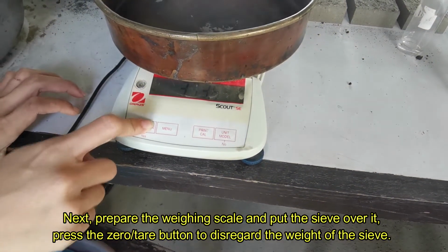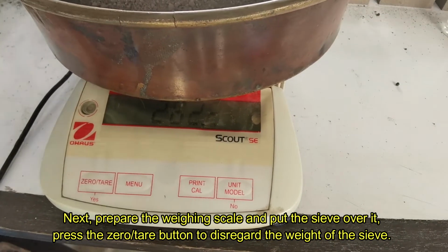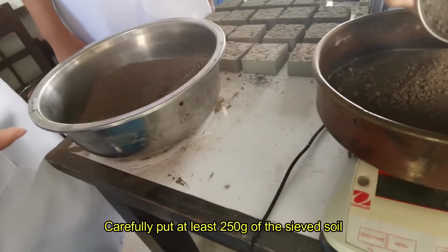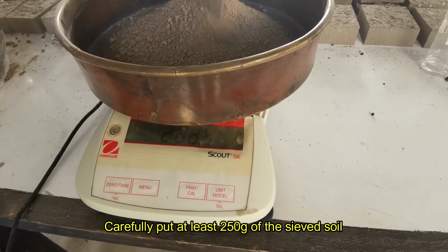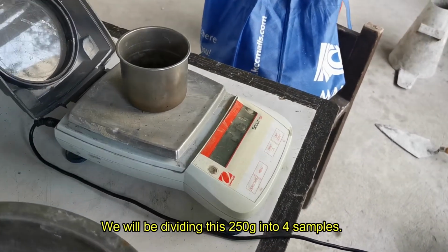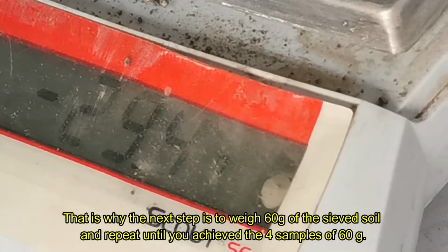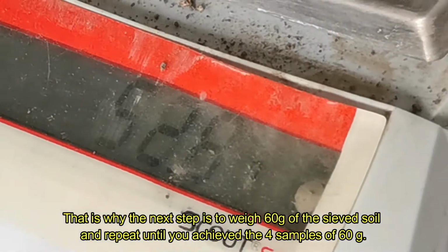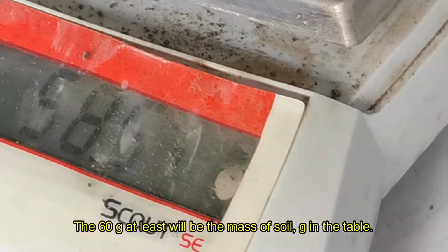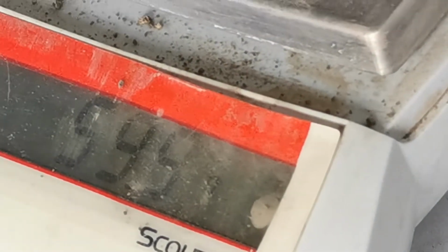Next step is to prepare the weighing scale and put the sieve over it. Press the zero or tare button to disregard the weight of the sieve. Carefully put at least 250 grams of the sieved soil. Now, we will be dividing these 250 grams into 4 samples. This is why the next step is to weigh around 60 grams of the sieved soil and repeat until you achieve 4 samples. Now, these 60 grams at least will be the mass of the soil, in grams, in the table.